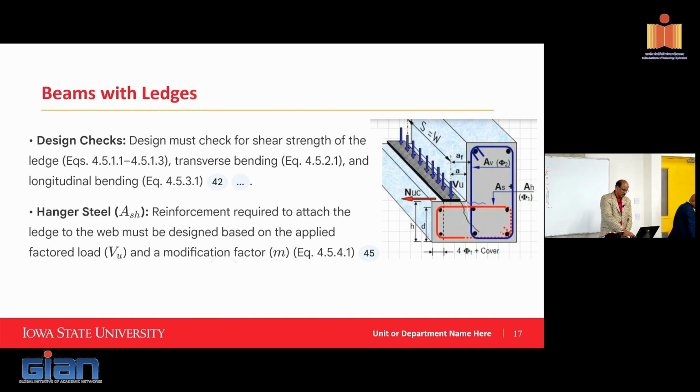And then you also need to make sure that you don't cause shear cracks. It's shown here: the moment you put in load here, you have a potential to cause cracking here and shearing of this section. So that should be checked, and make sure that you provide this additional adequate steel.